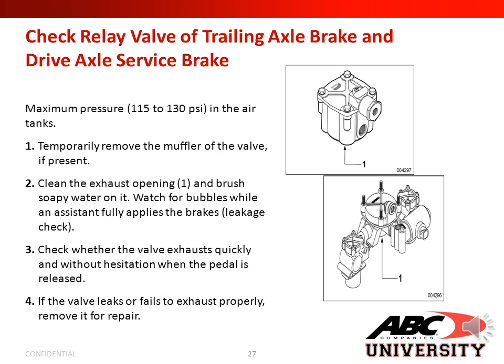Once you've cleaned the opening, number 1, brush soapy water on it. Watch for bubbles while the assistant fully applies the brakes. Check whether the valve exhausts quickly and without hesitation when the pedal is released. If the valve leaks or fails to exhaust, properly remove it for repair.